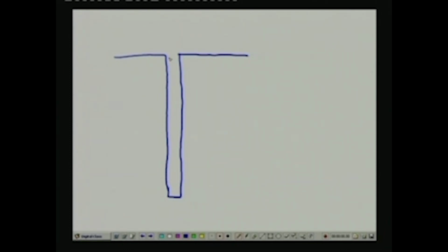So, what is done here is to extend a relatively small diameter borehole into the ground, and the top portion of this borehole is often supported using a metal pipe, so that the soil after the borehole is drilled, it does not collapse into the borehole.